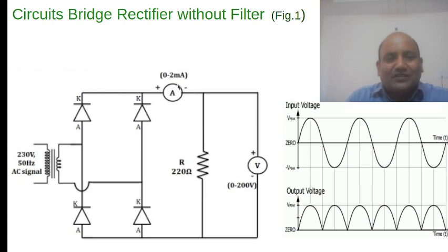Instead, it enters the ammeter which is connected here. Through this ammeter, current reaches here. This current will not go to this side, because this multimeter is connected in voltmeter arrangement. A voltmeter offers infinite or very large resistance, so current will flow through the load. Where current is entering, due to the convention, this end becomes positive, this terminal of the load becomes positive.